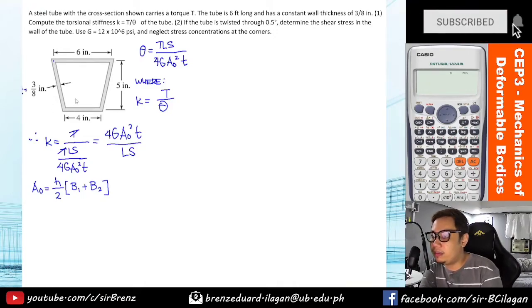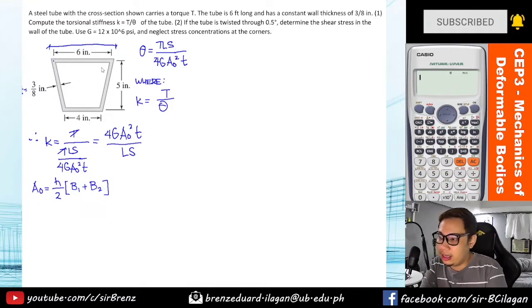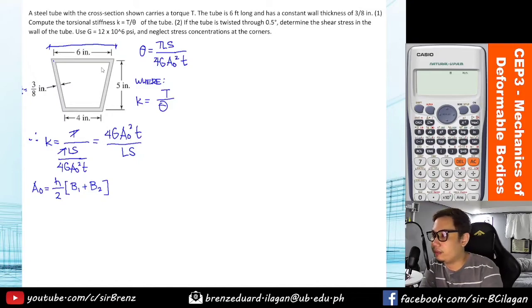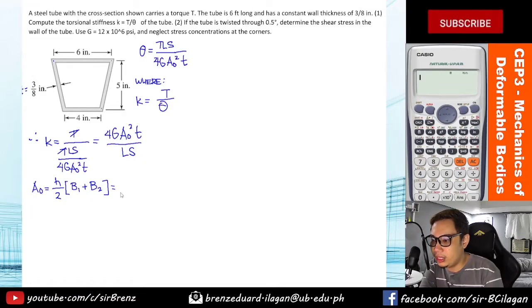But there are some problems where the measurements are end to end, all the way to the edge. When that happens, you need to deduct or subtract half of the thickness at each side in order to determine the dimension at every midpoint of the tube. Since the dimensions here are given at the middle, we won't have a problem. The H, which is 5, is already at the middle.